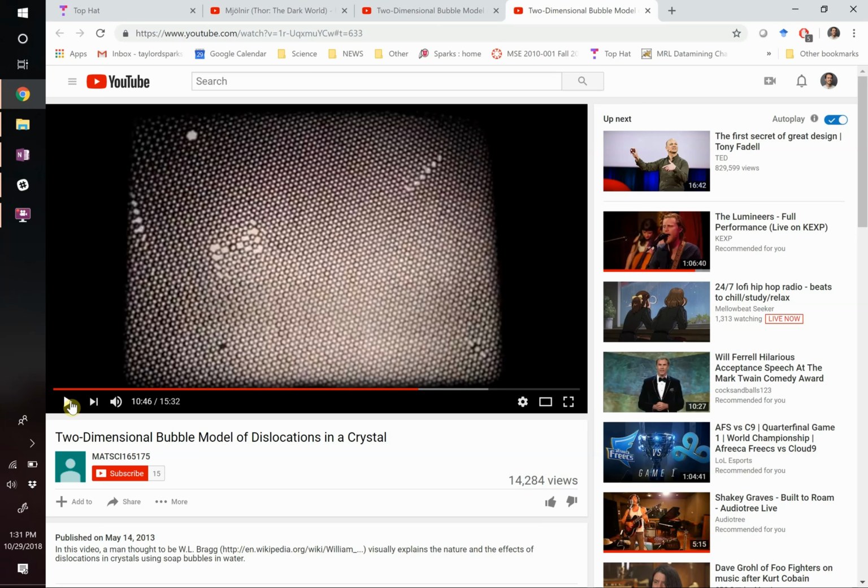All right, what do you guys think? How does this make it harder, stronger, more scratch resistant? If you have the imperfection in there, and it creates a compressive force around it, if it's bigger, then the dislocations are attracted to it, like the compression is attracted to the tension, that would counteract it, and I would think it would make it stronger. Oh, you're real close.